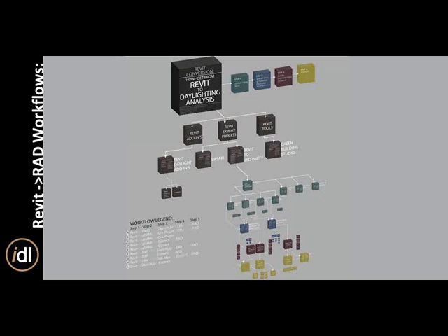So the question is about, can you automate or can you use material properties from previous projects and use those in future projects down the road? And it really depends. Like with Radiance, if you're on the back end, there are material libraries and schedules that you can use and just plug in from a text mode environment. OpenStudio, you can templatize a lot of the material properties and libraries that you do, so you can reuse them. Same thing with Ecotect. There are even some examples where you can organize everything in a spreadsheet and import them into something like OpenStudio. So to a varying degree, yes, depending upon the different workflow pathways that you choose.